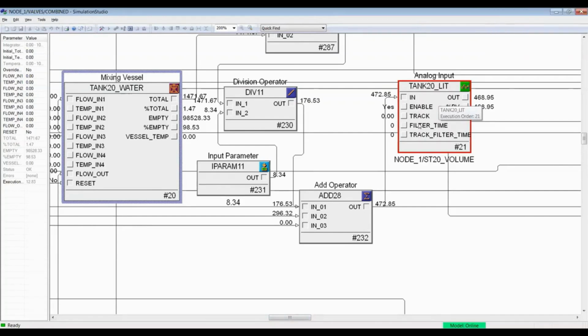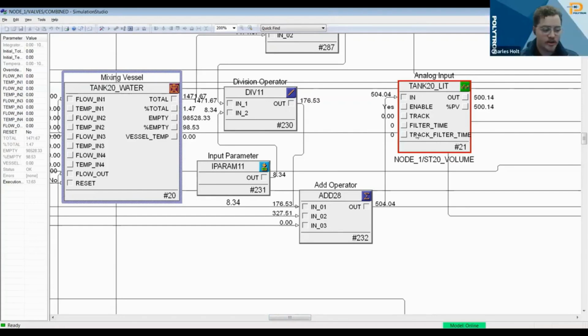So Charles, how did you build this model? Do you care about what the code is, or what type of processor it is? No, none of that really matters in terms of what Mimic needs. Mimic just takes everything from the PLC, including all the outputs, and then writes everything back to the inputs. That processor could be a Siemens processor, it could be a Rockwell processor. Here for Rockwell, we're using OpenOPC, which is just writing directly to those tags.